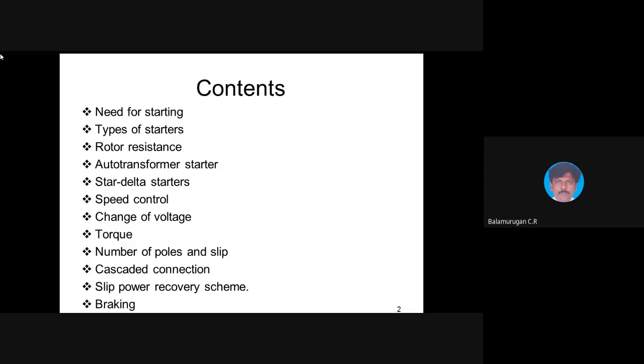Used to protect the machine. Okay, all these answers are almost correct. Any other answer? Limit the current to reduce speed. Any other answer other than this? You can tell as per the point of series, that is 2 point, 3 point, 4 point. It's enough, after discussing the AC you will be familiar. Each and every starter will have some specific advantage and disadvantage. To limit starting current, this is the exact answer.